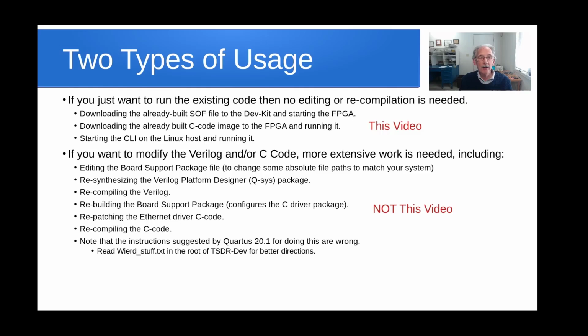You can also modify the Verilog and/or C code, but more extensive work is needed, including editing the board support package due to some hard-coded file paths in that package, resynthesize the Verilog platform designer, sometimes called QSys package, recompile the Verilog. You'll need to rebuild the board support package, which configures the C driver.